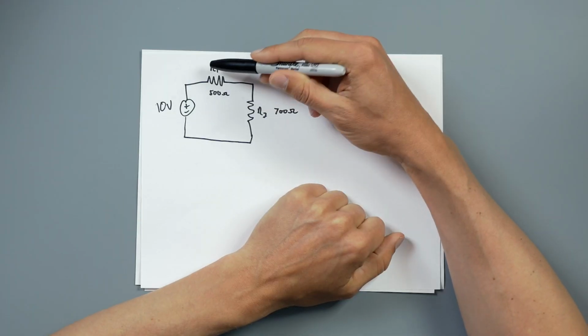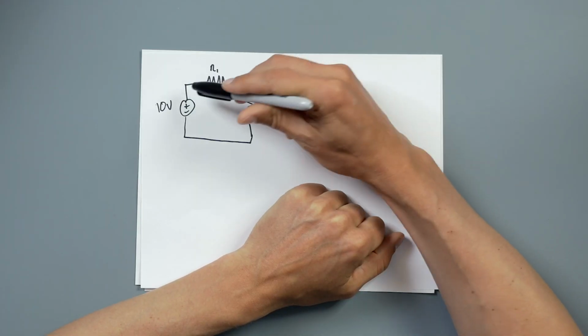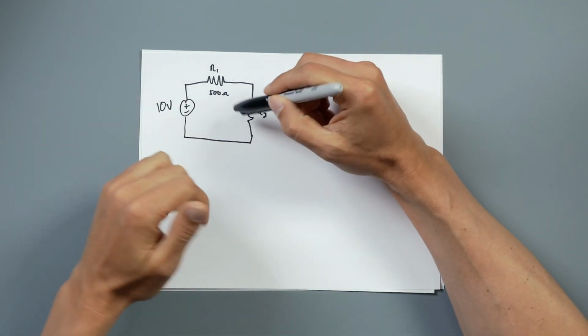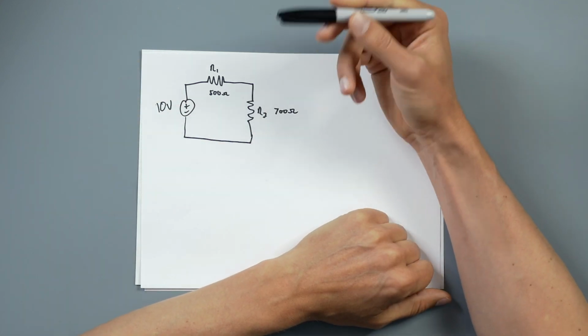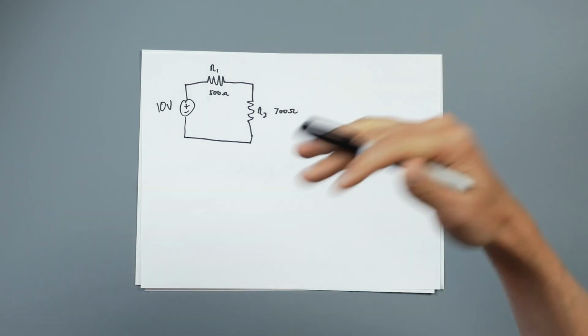So that final step should be, even if you are using your matrix calculator and LTSpice to double check your work, take a moment to say, does this make sense? Do these numbers work? If I have a bigger resistance, should I have a bigger voltage across it if it's sharing current? If I have a smaller resistance and it's in parallel with something, does it have a larger amount of current going through it? Those sorts of questions, 1, will make it so you're more likely to find out if you screwed up your math, and 2, help give you a better intuitive understanding of what you're doing. And that is the 5th step.